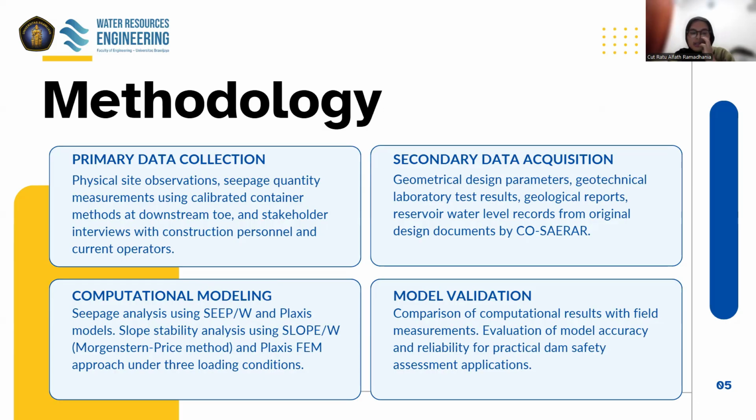For the third step, we have the computational modeling: seepage analysis using SEEP/W and Plaxis models, and slope stability analysis using SLOPE/W and Plaxis approaches under 3 loading conditions. And the last step is the model validation, comparing computational results with field measurements, to evaluate model accuracy and reliability for practical dam safety assessment applications.